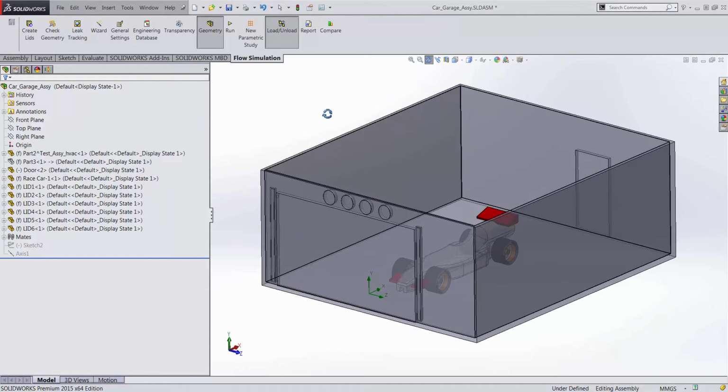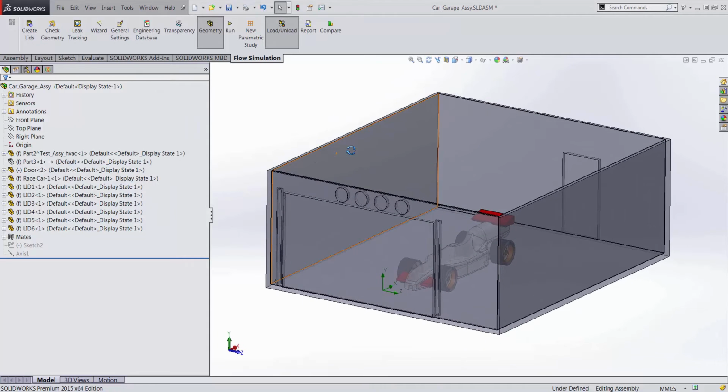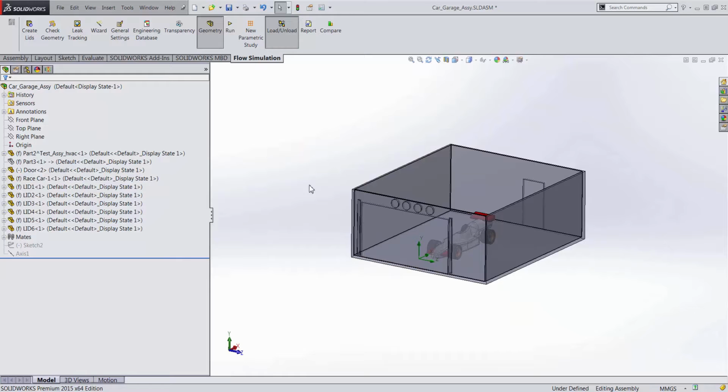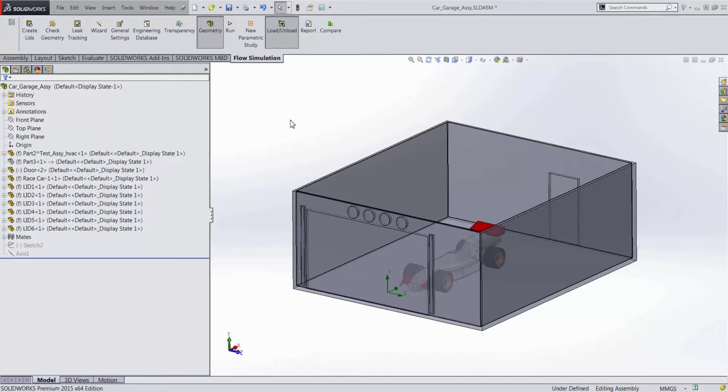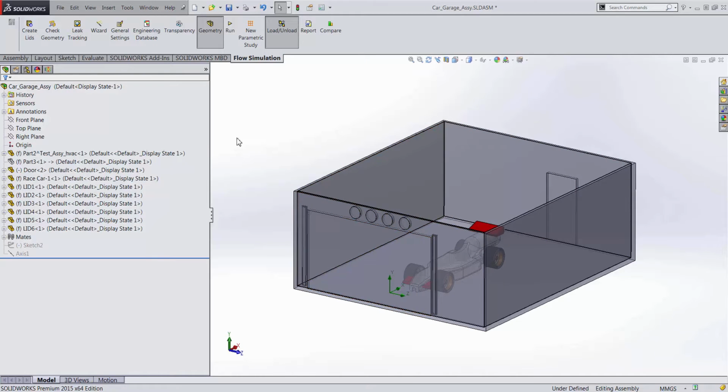And there's one thing I missed out. Prior to starting the problem, essentially you'd like to understand only what's happening inside the system and you don't really care about what's happening in your environment. Typically, this is what we call an internal analysis. And prior to starting off any internal analysis, it's good to see if you have a closed watertight volume.